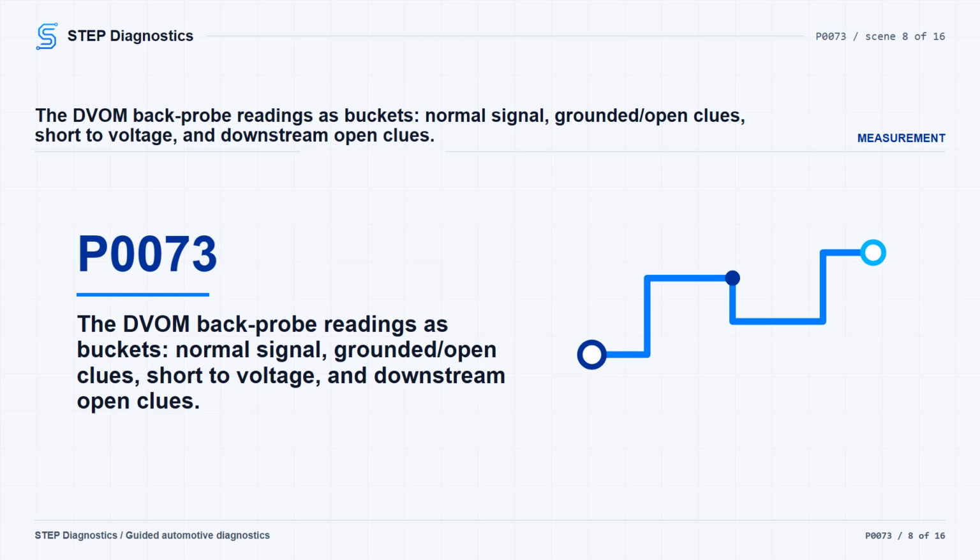If the signal circuit checks good, inspect all connectors in the system for pushed out, spread, corroded, or dirty terminals before condemning the ECU. To check the sensor side in this conventional path, move the test lead over and back, probe the temperature sensor ground circuit at the sensor harness connector. If the next return point is not clear, pause, recheck the earlier diagnostic path, and avoid guessing.